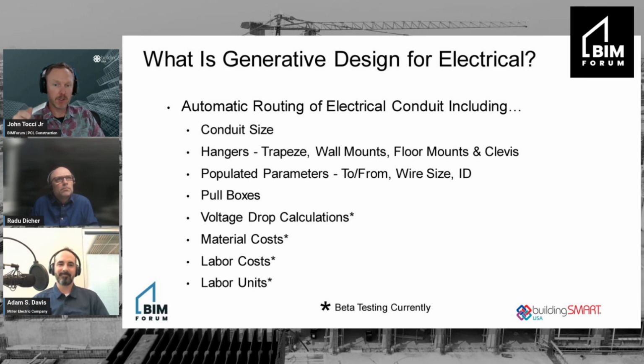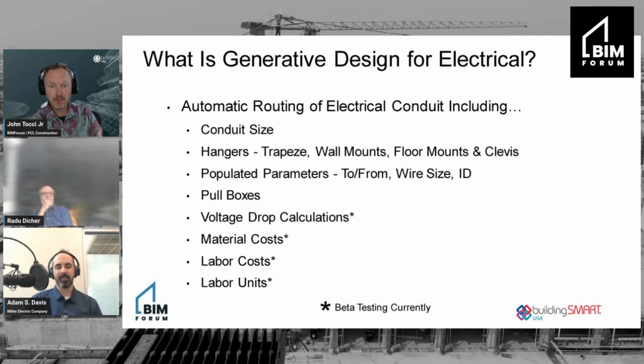But then you have the voltage drop because over the length of the wire, you lose voltage to the resistance of the conductor itself. So then the conductor has to get larger, right? And then the conduit, to maintain its fill capacity, has to get larger. And then you've got the added complication that you can only execute X number of bends, and I think code, generally speaking, is 360, but certain owners or engineers may have requirements for less than that.